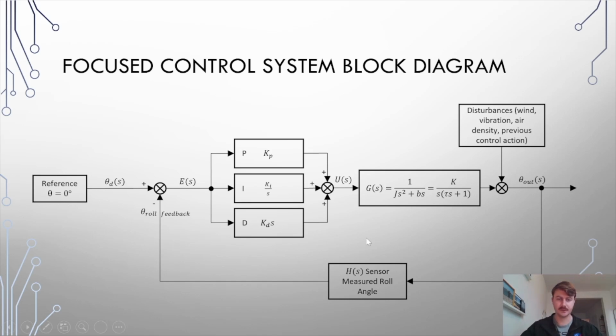So a PID functions essentially by manipulating the error in a predictive and a past data-based style. The proportional term is just a proportion of the error directly, so that responds to now. That will have a very fast response rate, but it will have a tendency to readjust a bunch of times because it has that fast response rate. So it'll overcompensate and overcompensate and overcompensate.